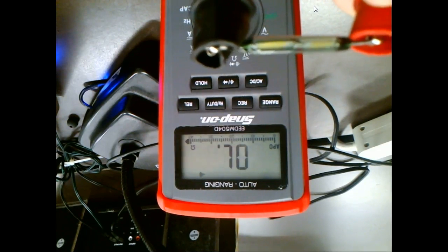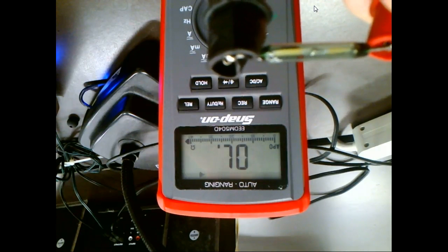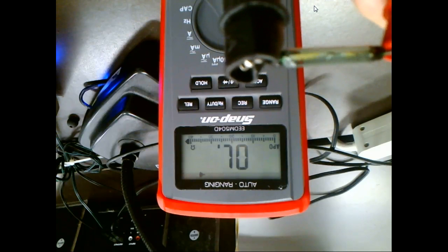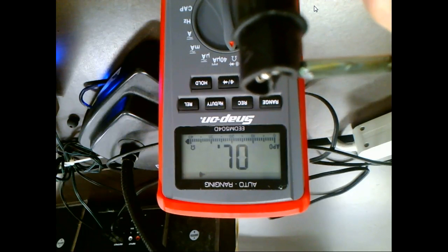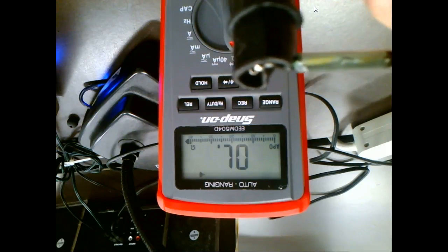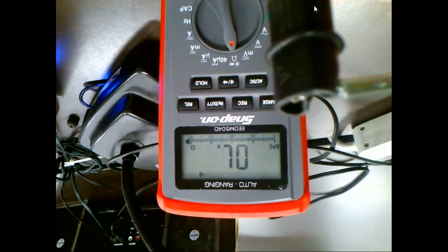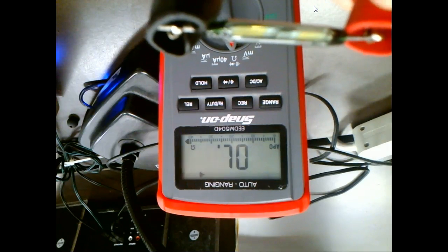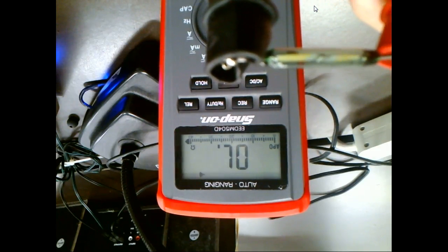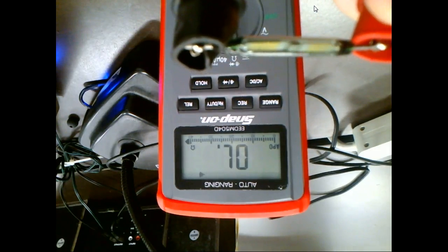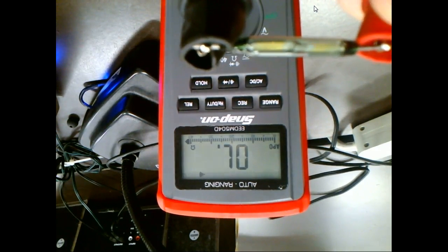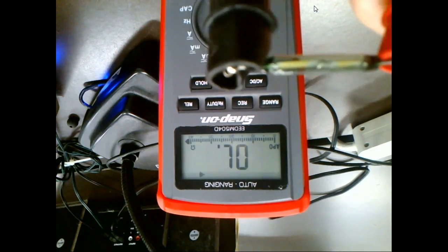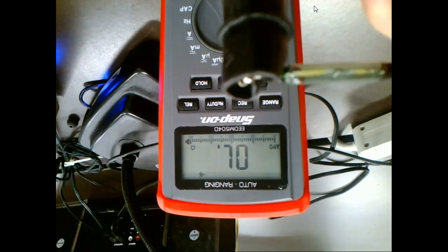Right, because it's electromechanical, right? It controls electricity, right? So like these guys could pulse and something can happen, and if I create an arc, it's like 32,000 degrees, it'll melt them contacts together in an instant. And then these guys you throw away. Relays you could break apart. But these guys, once they're welded together, you might beat them, break the glass. But, so they're electromechanical, or they could fail mechanically, right?